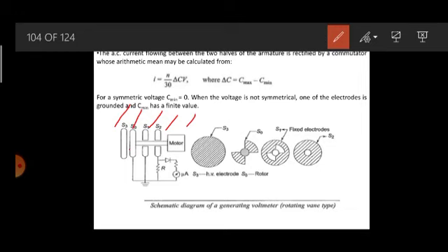You can see there is a gap between S0 and S3. S0 and S3 are your electrodes, and the air in the gap between S0 and S3 acts as a dielectric medium. So when we rotate S0 at some constant speed, there is a change in the capacitance between the insulated disc S2 and the high voltage electrode S3. I hope up till here it is clear.